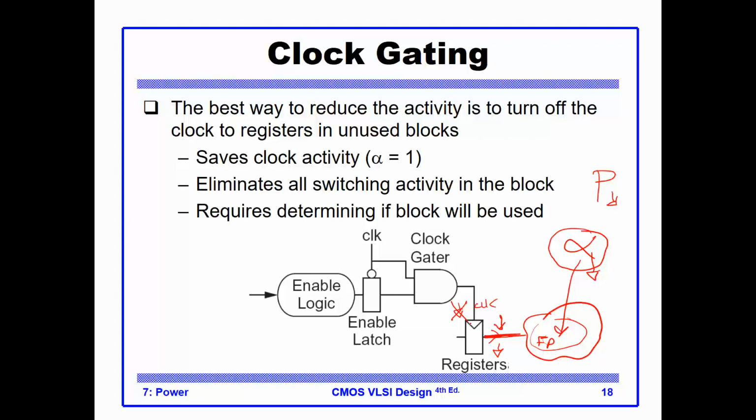Now, there's an interesting thing here: how do we create this enable signal right here? The enable latch is an extra circuit that needs to be switching and burning power, which is kind of interesting. We wanted to reduce power, but we ended up creating an extra circuit, which will add more area and more power. Well, that's why you have to do these things very, very carefully.